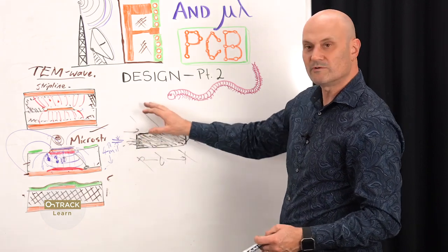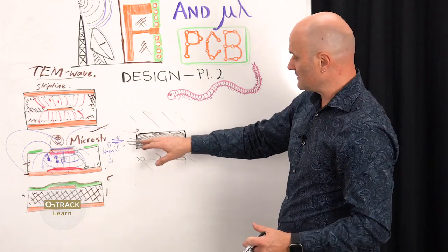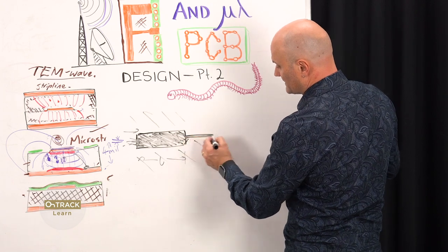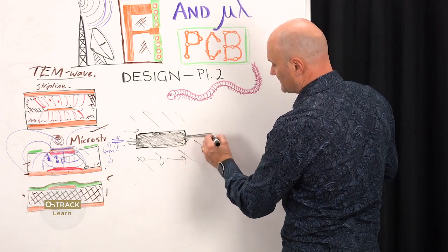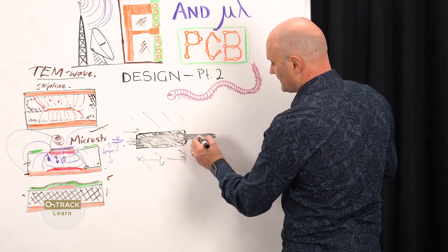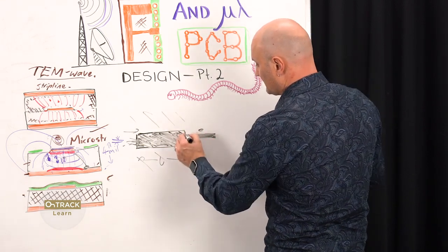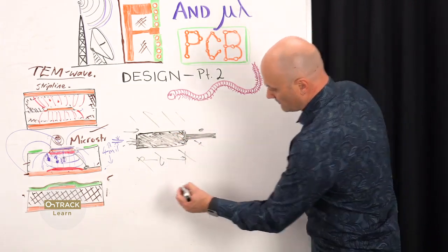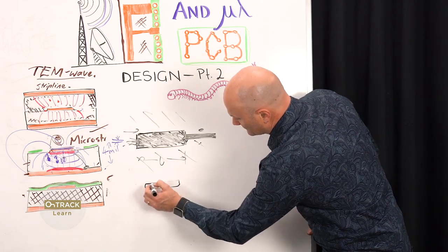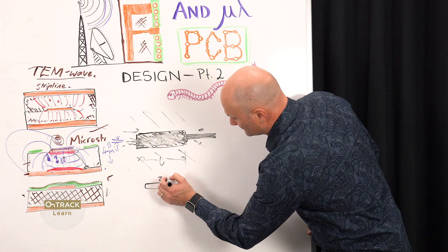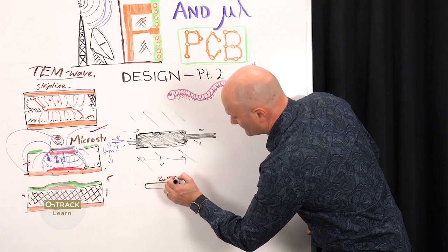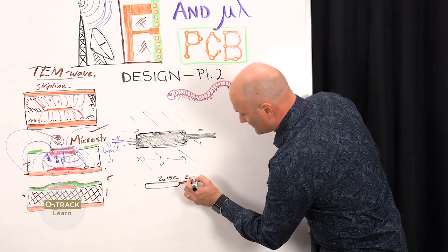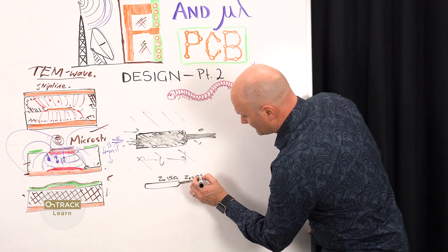It's maybe a 2.4 gigahertz wave going into this trace, and then somewhere down here, down the line, we come to a much higher impedance trace that's narrow. Maybe we have to neck it down to fit in between two pins or something. Well, this here is an impedance anomaly, and we know what happens when we create a transmission line of one characteristic impedance. Let's say that Z0 is 50 ohms, and then here we have a narrower trace. Maybe that Z0 of that one is 100 ohms.